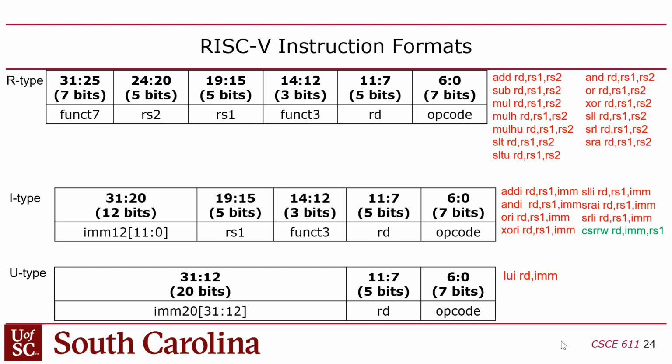So in other words, normally you have 32 registers, but this instruction exposes another register file that's 4,096 registers, essentially. Of course, we're only using 2 in this lab. One is the hex displays and one's the switches.